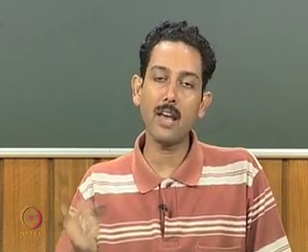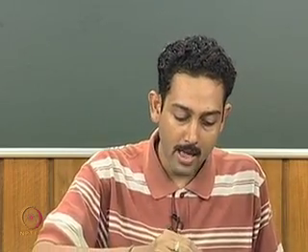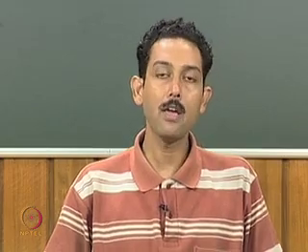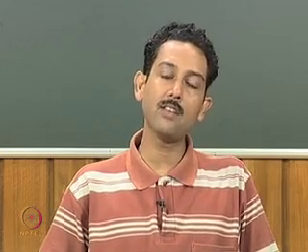As in a very similar case like modular LFSR or standard LFSR, whatever you take, the basic idea is that you can generate a near exhaustive set of random patterns, and the area overhead is very less. In this case, as you can see, only one XOR gate is involved, but in a standard LFSR, there is a feedback from the last flip-flop to the first flip-flop. The longest feedback in a standard LFSR involves a sequence of XOR gates, so that was leading to some kind of delay.